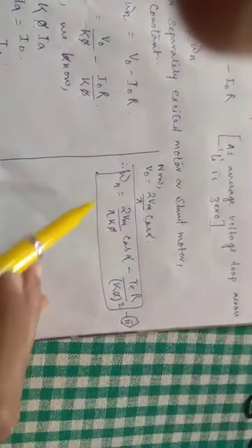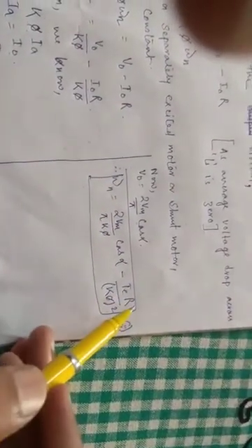So from this equation we see that it's a straight line equation, with R by K phi square as the slope of the equation, and it varies with alpha. As you vary alpha, this omega n will vary, and torque is an independent variable while omega is a dependent variable. As you vary the torque with a particular value of alpha, the omega will vary with a different slope, omega n.